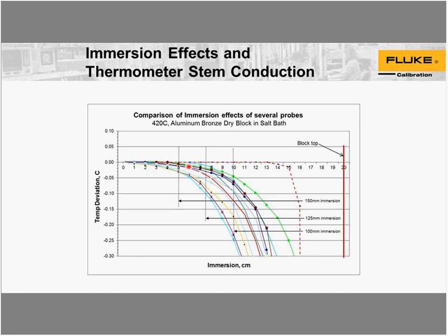So every meter or so I'm taking a measurement. But what's happening here is, again, these sensors are different designs. They have different lengths, diameters, different types of lead wires, that sort of thing. You can see that even though they're apparently at the same temperature, the indication of temperature is varying. Okay, this is 20 meters depth.